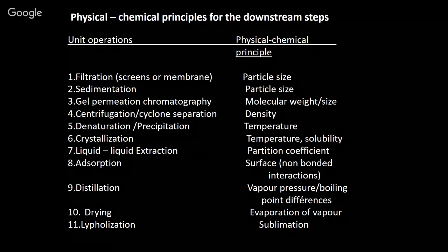I talked about the reverse micellar extraction, where I'm using a surfactant. Although I use a solvent, the protein doesn't get denatured because I have surfactants which capture the protein and maintain it in a polar environment. So I can use liquid extraction, aqueous two-phase extraction, or reverse micellar extraction for removing metabolites, proteins, biomolecules, and peptides. Partition coefficient plays a very important role in this situation.